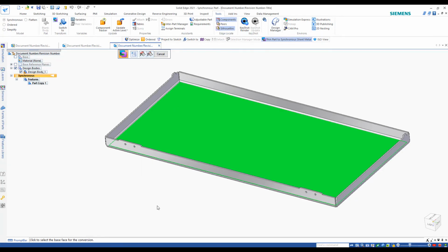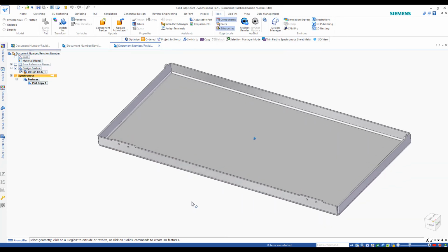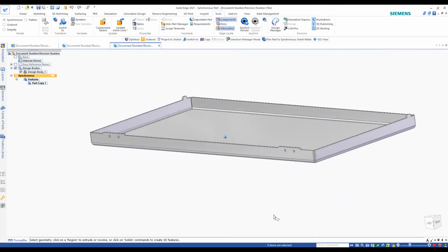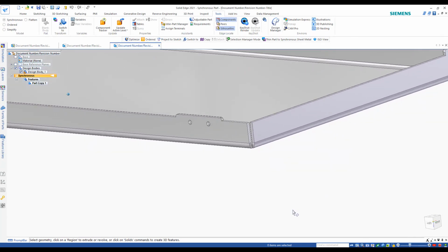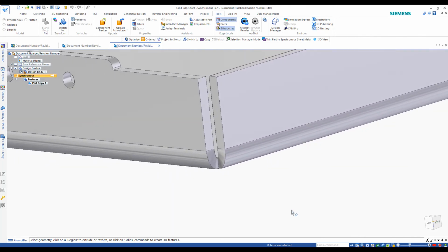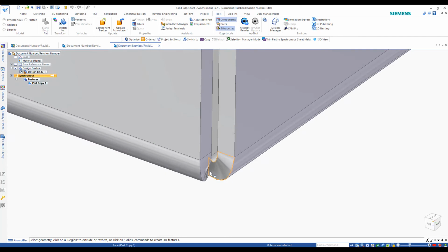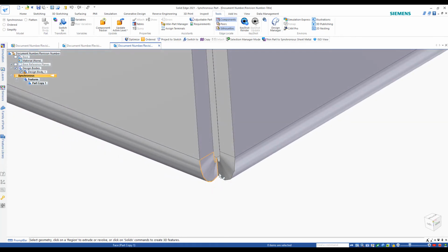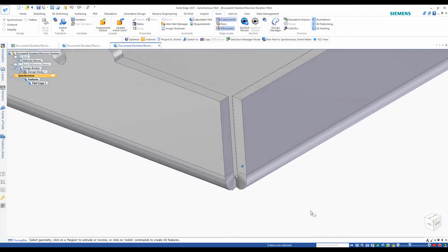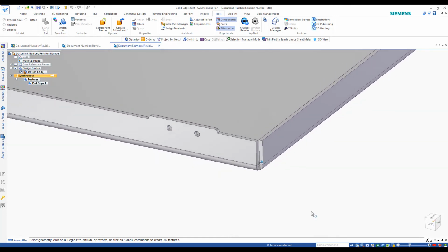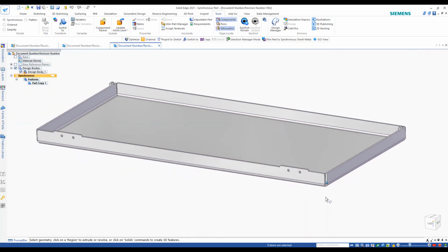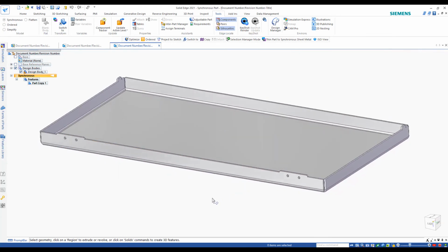This one's not as easy to see, I guess, looking at it from afar, but again, I typically will go to the corner conditions and see what's going on there. And if you look a little bit closely at these corners, these radii where these bends are coming together, they look a little odd. So what I'm going to do is go through, and I'm actually going to take this part to a condition where it's almost like a box with sharp edges.